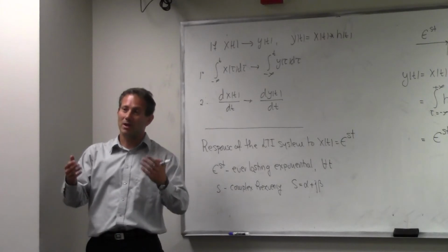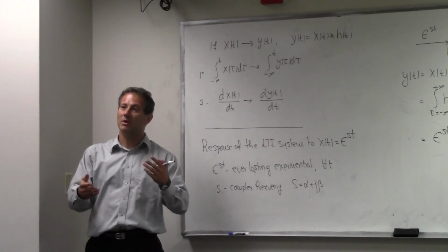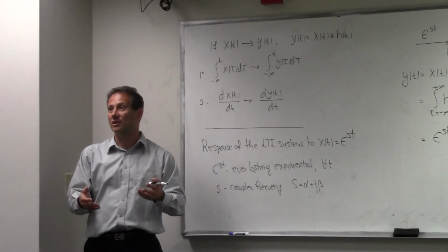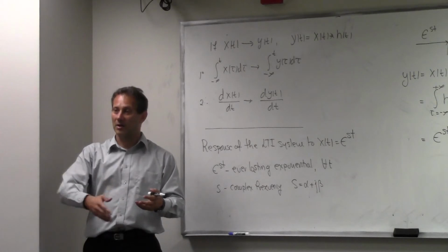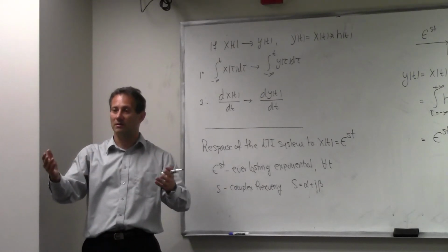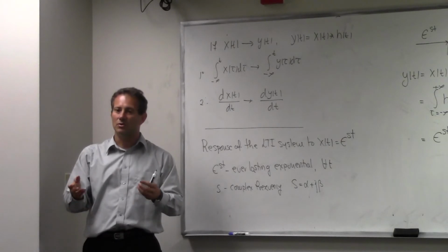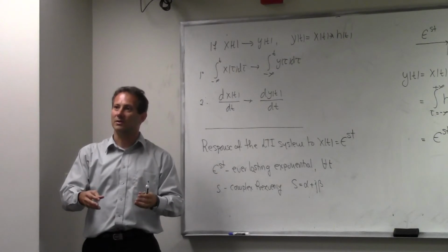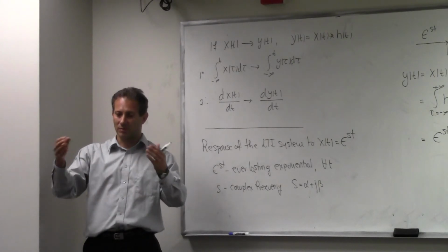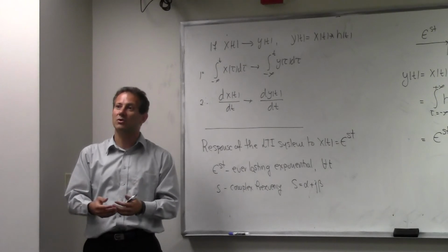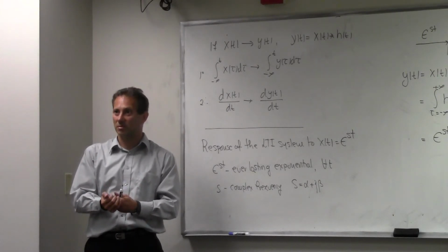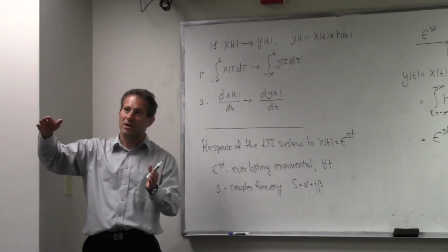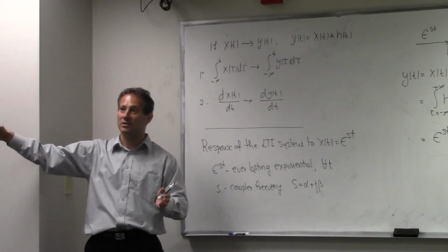No. Because the way we build amplifiers, we use a whole bunch of active components. Active components are notoriously nonlinear. If you look at a transistor, the output is exponential, right? If you look at diodes or everything that's in there, you have some sort of nonlinearity. We spend a lot of effort making sure that our amplifier behaves as close to a linear system as possible. But it never gets there completely, or it gets there within a certain range, but then it flips, right? So outside of that range it is nonlinear.